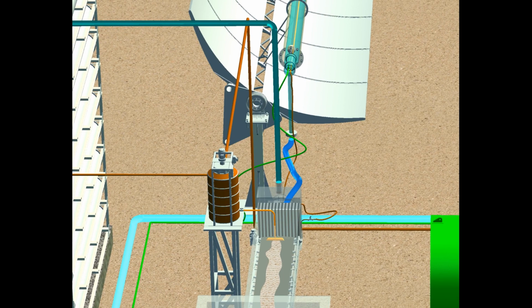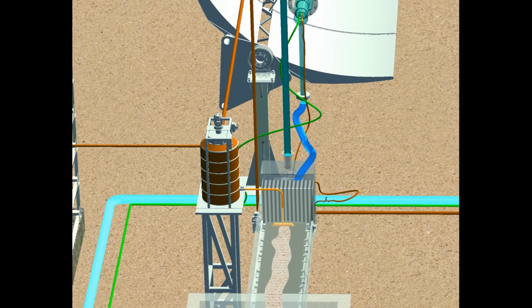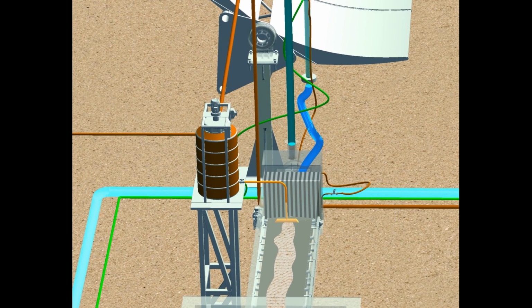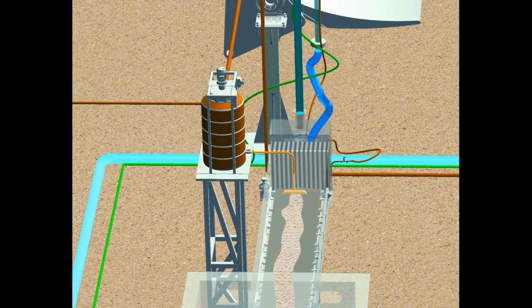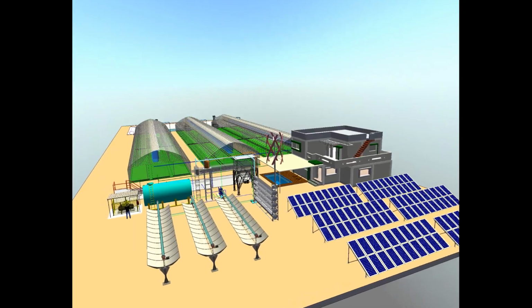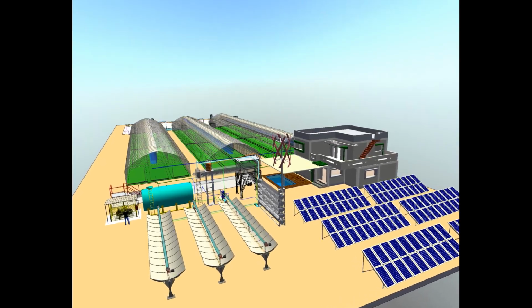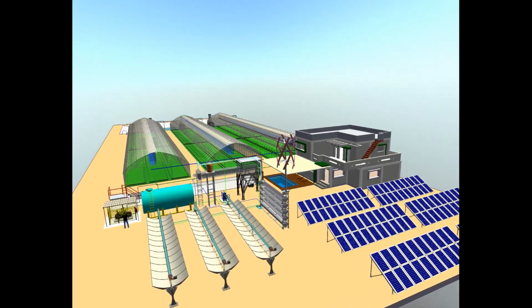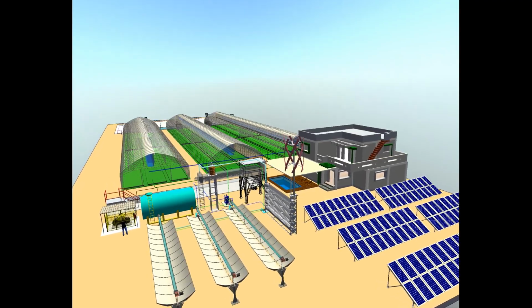Secondary steam of the last 10th stage with a pressure of 143 kilopascals and a temperature of 110 degrees is sent to the steam air condenser and heats the air, which is used to dry the salt concentrate to the state of dry salt. Of course, the use of solar energy as a heat source for film evaporation drums is only a special case for regions with very high levels of insolation. And for this case, it is most rational to use a multi-stage connection scheme for film evaporation drums.